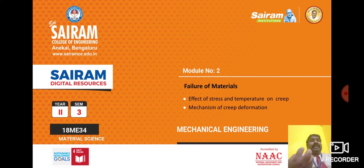What is meant by creep rate? The secondary creep, or stage 2 of the creep curve, is of the longest duration, and the steady state of this creep rate will be the most important parameter of creep behavior in long life applications. An example is a nuclear power plant component that is scheduled to operate for several decades, where failure or too much strain is not an option. So this is how the creep rate comes into play.